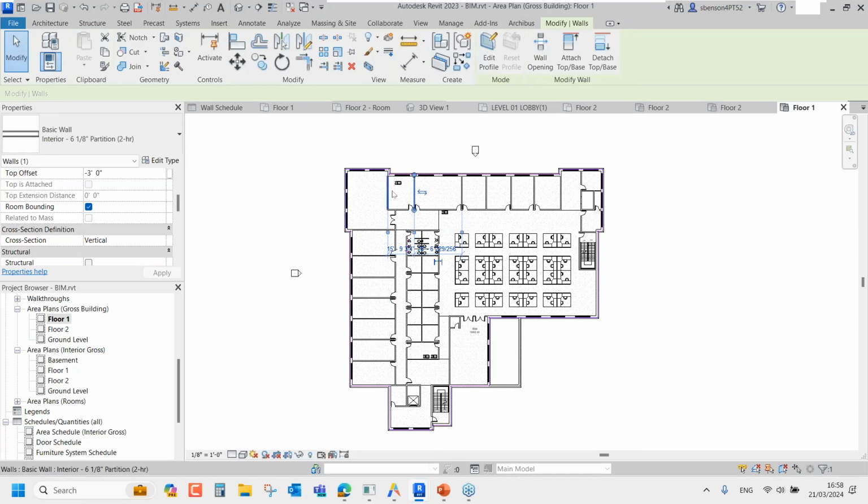Then you want to make sure everything is tagged. Tagging means you need to make sure that you have a tag that you can pull into Archibus. We had a client recently whose room tags included their building, and it made the room ID about 10 characters. And Archibus has an 8-character default out of the box. So automatically that is going to be difficult to synchronize with Archibus, because you're not going to be able to pull those 10-digit room numbers from Revit into an 8-digit Archibus field. So again, go through and make sure that your tags are set up correctly, you determine what fields you're going to use for signage, and then you tag all your equipment, making sure the appropriate Archibus primary key is included in the model.